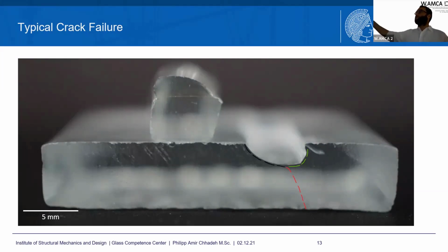I would prefer not to see the line at the interface, but I think this is obvious. Yes, we often saw this, and I would believe that this comes from the glass strip not shearing off clean, because we had enough heat to bond it, but on the other part, due to the rotational aspect of the test, I think it also favors breaking through the glass plate there.